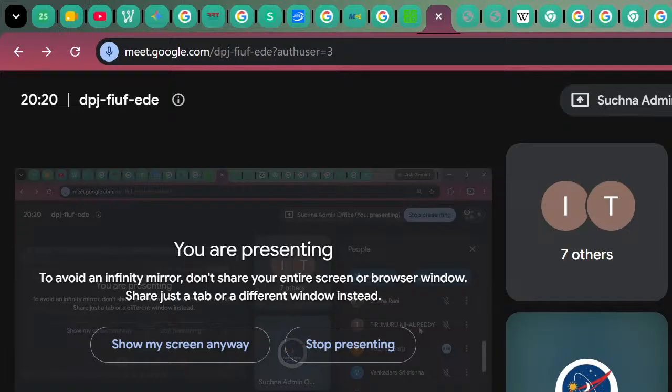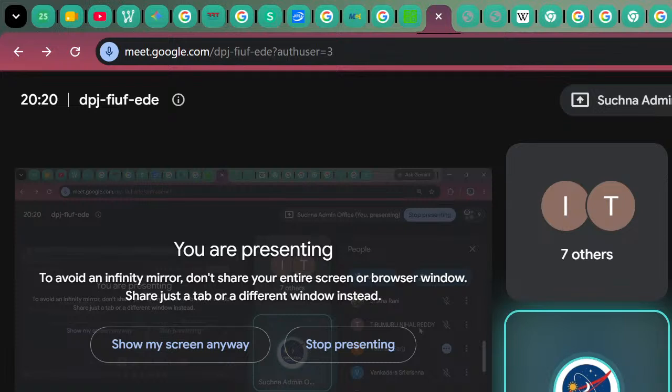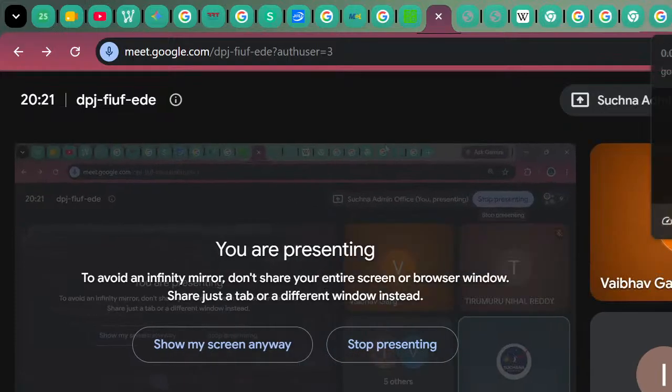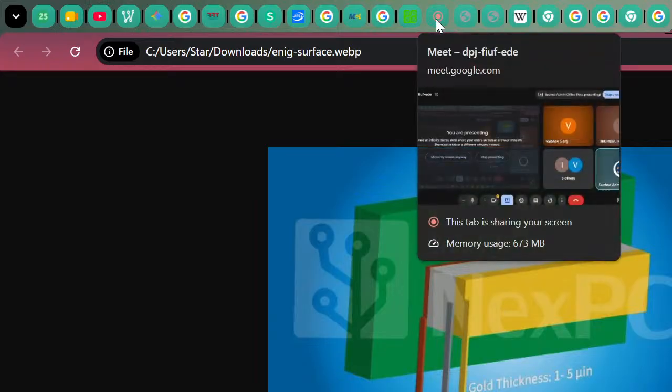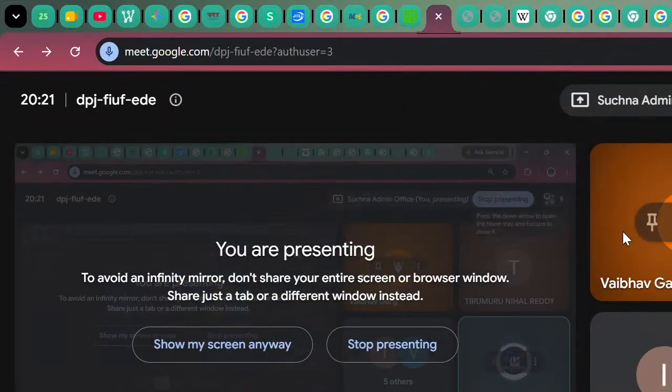Perfect. You only need to remember electroless and immersion. You know about nickel because the nickel material is used, and gold. ENIG, G means gold. Electroless, nickel, immersion, gold. Only need to remember electroless and immersion. This is the ENIG, electroless nickel immersion gold method. Is it clear up to here? If it is clear, now we need to discuss one more test called the tape test.